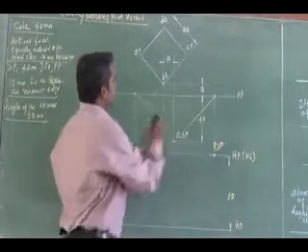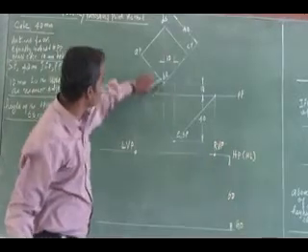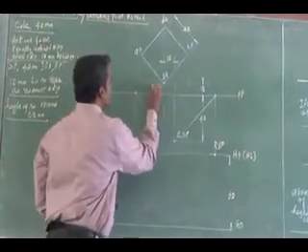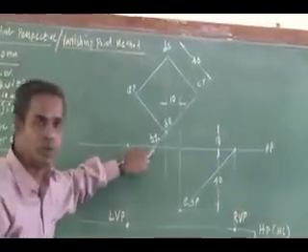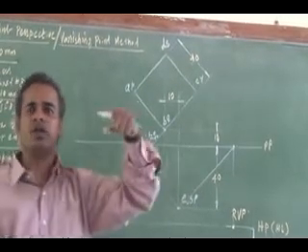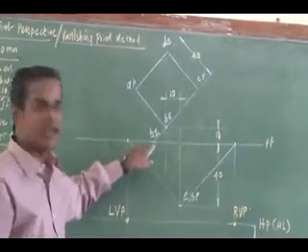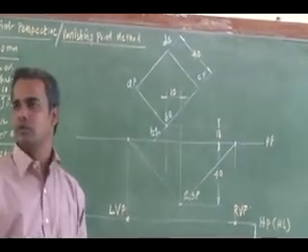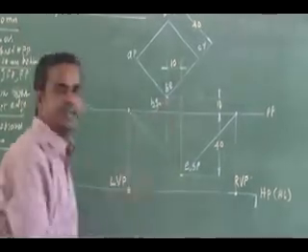So now I am extending parallel to the right vanishing point. Is it clear? Now this BQ, I am getting an arbitrary location. It meets here, that is my location, say B2, Q2. Now this B2, Q2, if I project it to the ground plane, that B2, Q2 edge will give me the true height in my perspective, isn't it? Since it is not touching, I am extending this BQ, assuming it, to get the true height in my perspective.